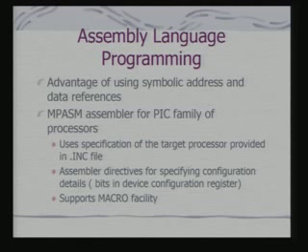So, we have seen more or less a variety of instructions, and we have also used some of these assembly directives. In assembly language programming, you use not only the mnemonics, because our discussions so far have been in terms of the mnemonics for the instructions of PIC, and these mnemonics get translated to binary code by the assembler, but the assembler also supports symbolic references to addresses and data, which facilitates your programming.